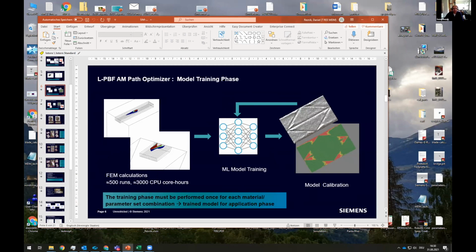Yes and no. The answer is actually we provide information about the preceding layers, but this is numerically homogenized. So we start from a quasi-static reference temperature. The solution happens in the layer, but we have information whether this layer operates at 100 or 150 degrees C from a layer by layer solution, as is common in industry. Okay, thank you. So thanks a lot.